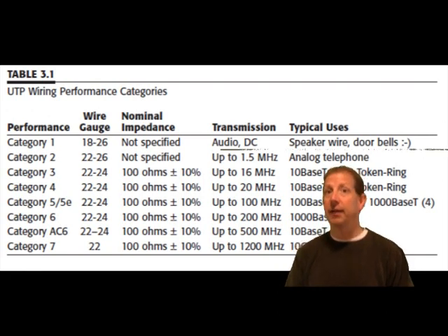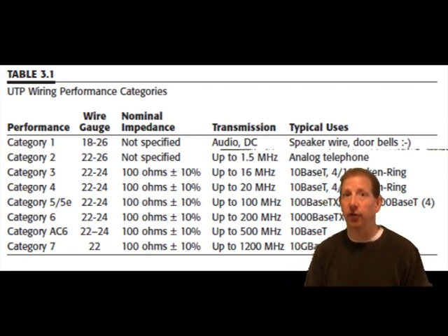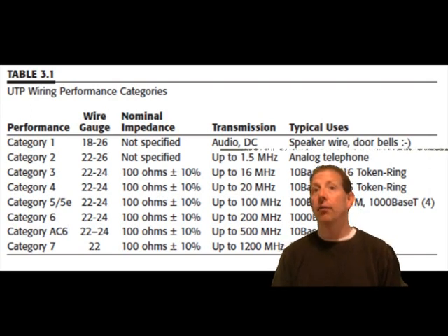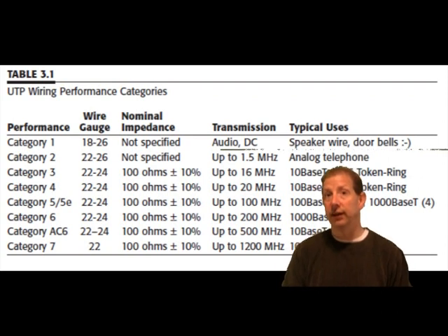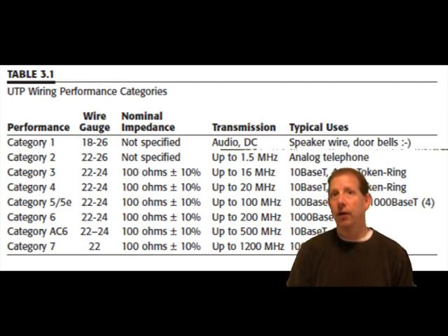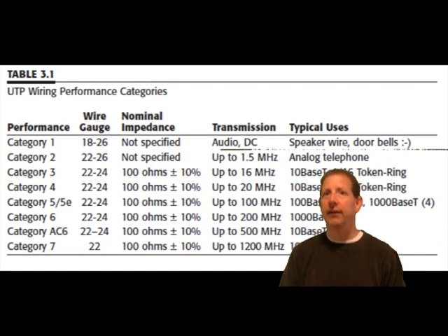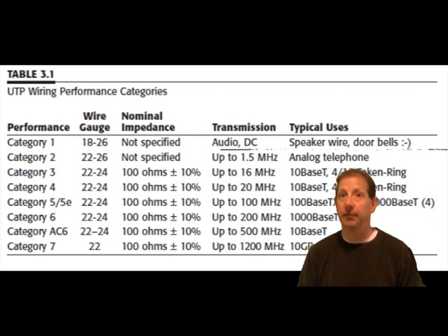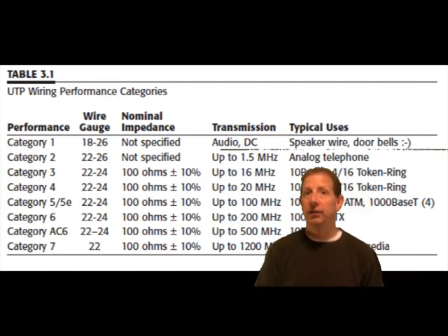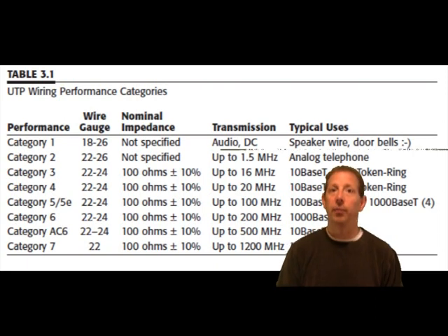Cabling devices are often rated by the industry in both bandwidth in megahertz or gigahertz and in throughput or data rate, which is meg or gig per second. Regardless of which number you see, the bandwidth of a component is the limiting parameter. This is because data encoding techniques often obscure the actual cable signaling rate, which is bandwidth limited. For example, the older 10 and 16 meg Ethernet and token ring networks required matching cable bandwidth of 10 and 16 megahertz because their signaling structure actually operates at those bandwidths.